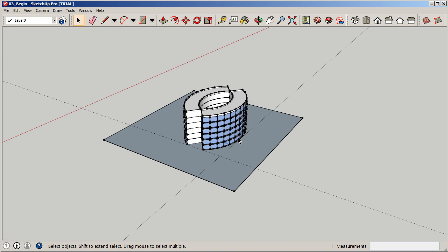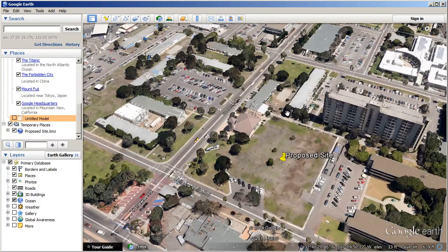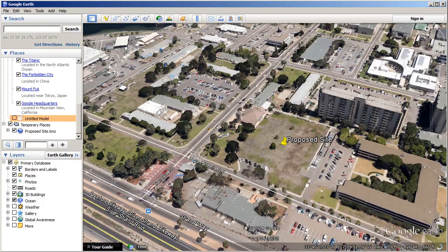So as I mentioned, our grid's going to be set up in tens. That'll be what we're using here, but we're not going to use it just yet. But keeping that in mind, we're going to go ahead and lay out some important references. So these are going to be our corners here. So if we go back to our Google Earth, here, we're basically going to set up our parking to where we have 30 feet of distance from the corner here to there, so people can see on the corners and we're not obstructing any sight triangles. Same thing on this side, same thing here, there, up here, and on that side as well. So 30 feet is going to be our magic number.